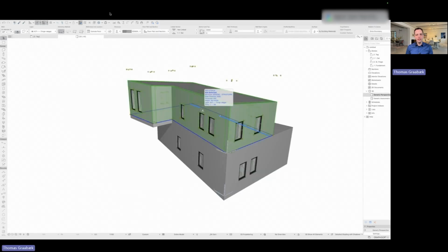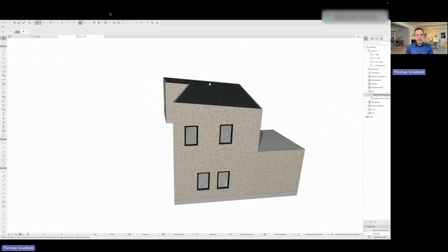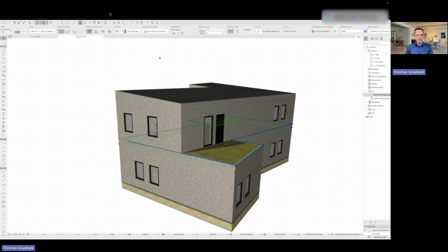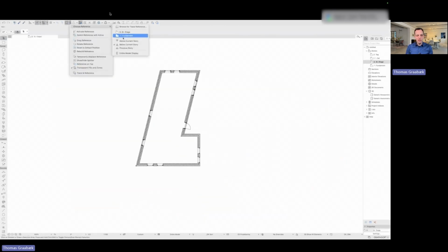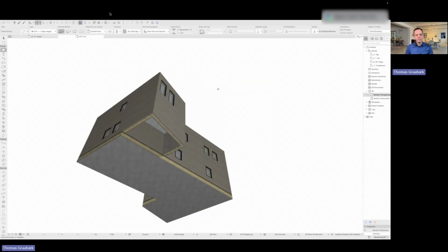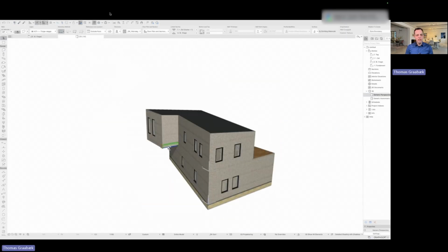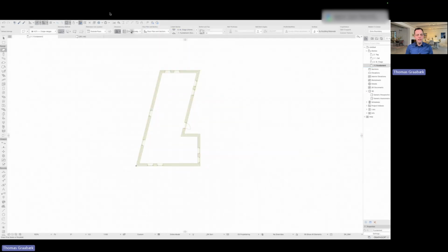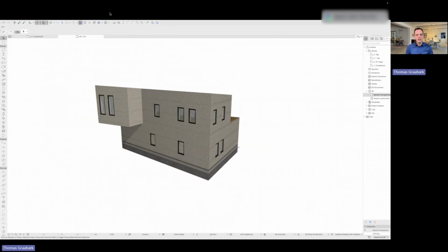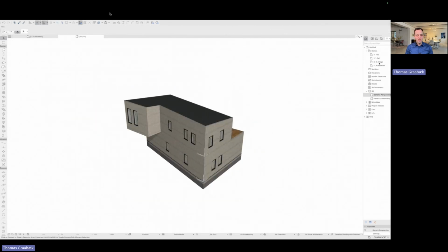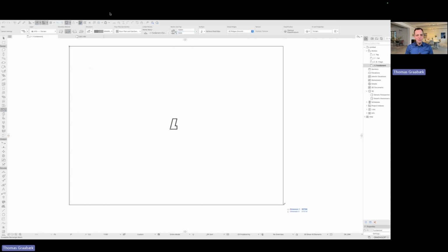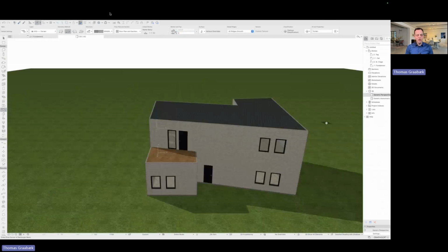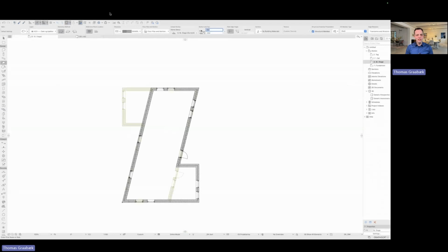And that means you can put composites on your project like I do here. You can see the exposure of the slabs, so I just want to fix that. Or otherwise, you can make your own materials with CO2 data and put them in your own template. And then when you model, it will automatically calculate the LCA. That's a very nice way of working, so you don't have to find EPDs, these environmental product descriptions from the producers of the materials, and enter the CO2 on every material every time you start a new project.